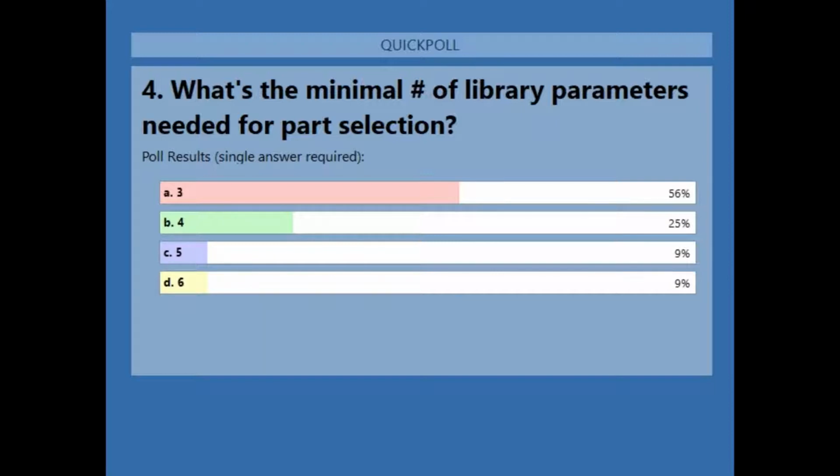Or a lot of times they'll introduce a new part and they'll just obsolete the old set of parts, and they just kind of go away, right? So we don't really have to worry about the first two. But when it comes to status and availability, that one's really difficult because it's a dynamic feature. To have a static parameter that you have to constantly maintain and keep an eye on is not an easy thing to do. Now, some of you may have access to something like Silicon Expert, and you have all your parts available to Silicon Expert, and Silicon Expert will flag those parts that they think are going to go obsolete or end of life. But even then, you're still going to have to go back into your library and make those changes to this particular parameter. So it's not an easy one to maintain.